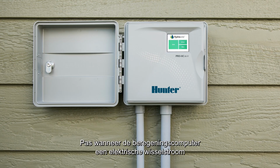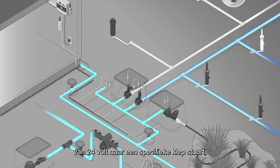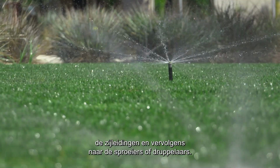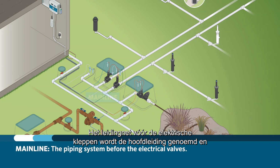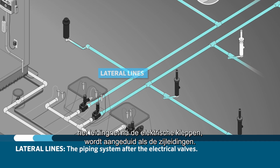Only when the controller sends a 24-volt alternating current electrical signal to open the particular valve will that valve open and allow water to flow from the main line through the lateral lines to the sprinklers or emitters. The piping system before the electrical valves is referred to as the main line, and any pipe system after the electrical valves is referred to as lateral lines.